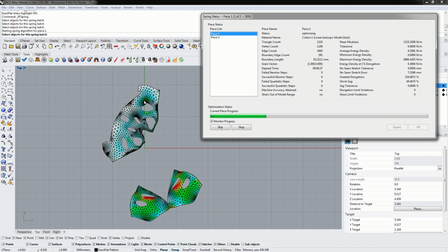We may also have problems with the optimizer because of the shape and the cuts that have been created. If we're trying to optimize extremely complex curved objects, with double curvature, very, very wavy, the optimizer may not be able to fully resolve it. In that case, you may want to look at splitting up your mesh to allow the shape to be optimized better.